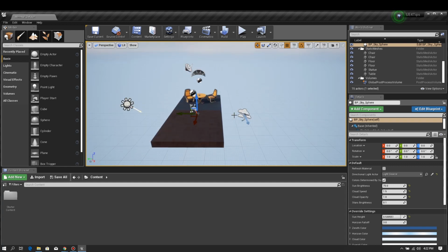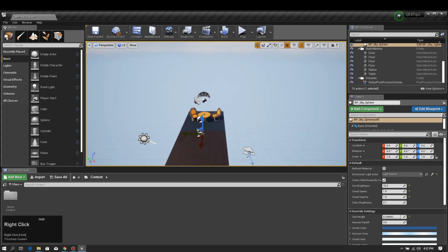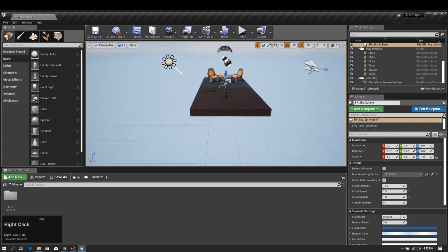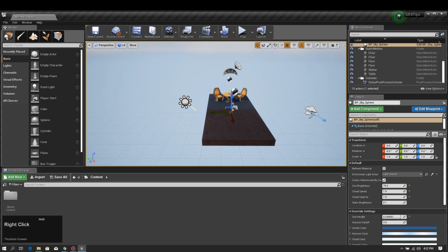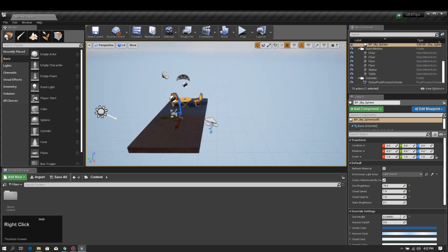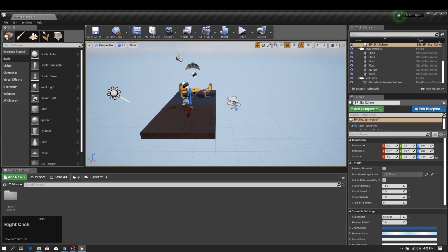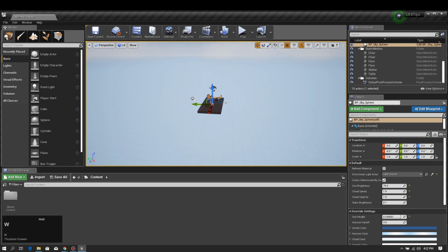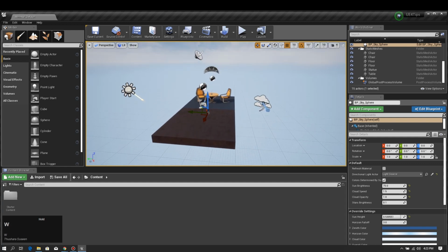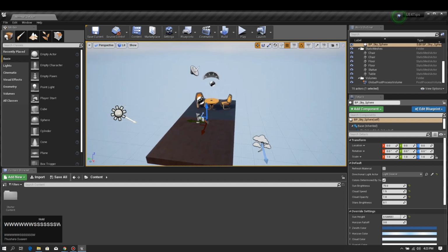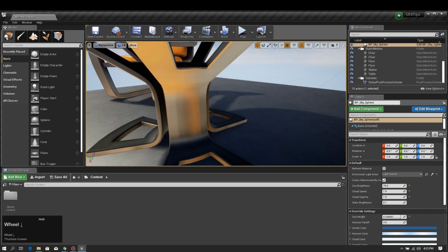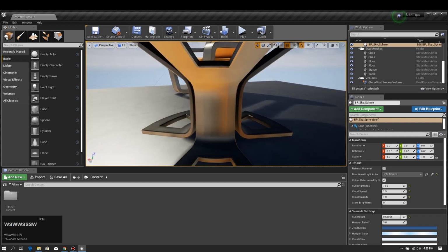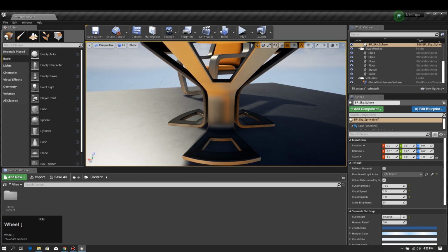There's another cool navigation where you press both left and right click and hold on to them, and if you move forward, you will pan up and down, and if you move your mouse left and right, it will pan left and right. Okay, I'm going to hold right click and speed up and slow down. Sometimes, if you are near an object, you may want to slow down the movement, so you can use mouse scroll down to do that.